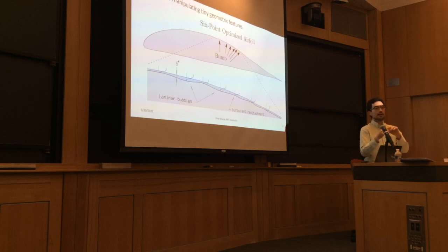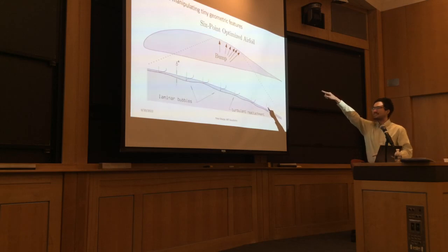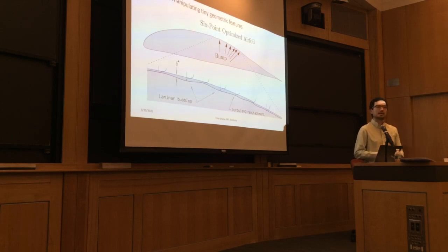And so they show that even in that case, you'll get tiny geometric manipulations to move that shock wave forward and backwards in a way that, again, is not really manufacturable. So although this effect is most prominent at slow speed, at high speed there are different effects that still cause a similar phenomenon, but from different physical mechanisms.